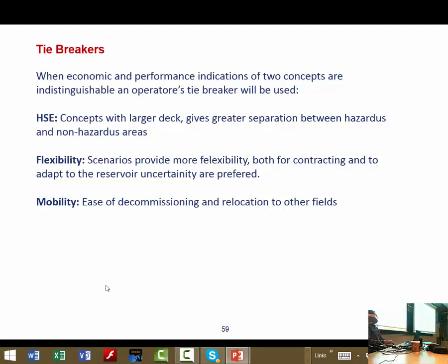Usually for a storm, no, we don't, because we design it for the worst case. We use the minimum draft and maximum draft, and we apply, for example, a 100-year storm or 10,000-year storm for both cases. But you have storage on the vessel. Yes, if you fill the storage tanks, it's going to go down. But the difference is not big because, for example, for Penguins FPSO, when the unit is empty, the draft is 16 meters because the ballast tanks are filled. But when the unit is completely full, the draft is 20.7 meters.